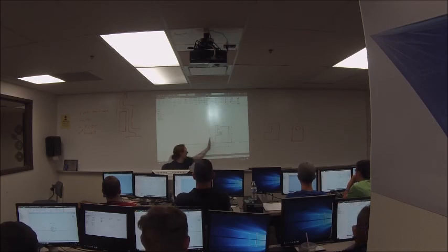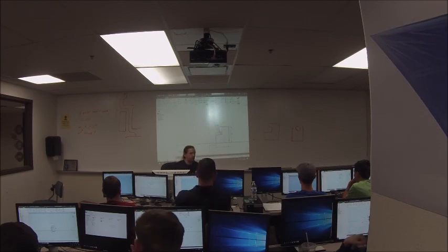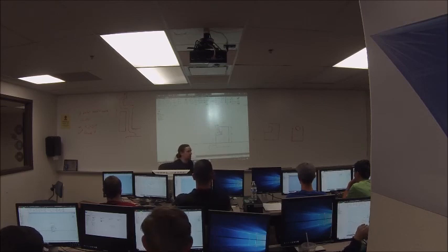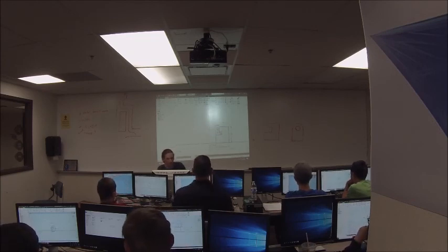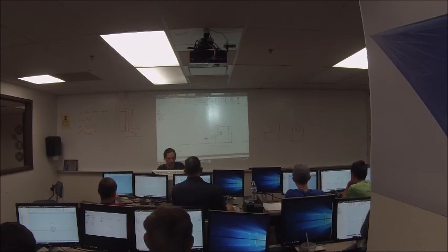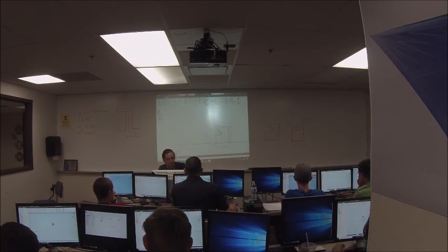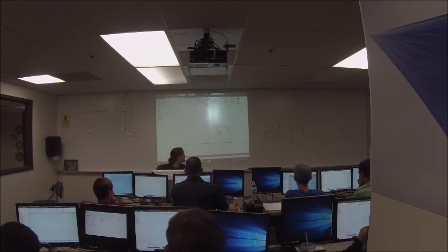So we need a line that will act as the axis of rotation in our sketch. Now the length of this line is not important. I'm just going to make it 1 inch long. But I'm going to go up here, I'm going to create a line, I'm going to click on the origin, I'm going to go straight up, I'm just going to make it 1 inch long, which you can type in the box while you're creating the line, then just hit enter. Or you can create the line and dimension it afterwards, up to you. Okay? Everybody got a center line?